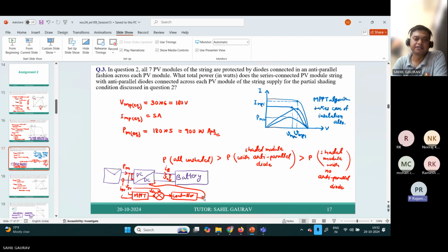Suppose I want to charge a battery with, say, 48 volts, sir. I want to charge it as it is, meaning I put more batteries in series with 5 amps current. Suppose, due to low insolation, I don't get the 48 volts. My output of the model falls down to say 30 volts. In that case, how will that control loop system work, sir?